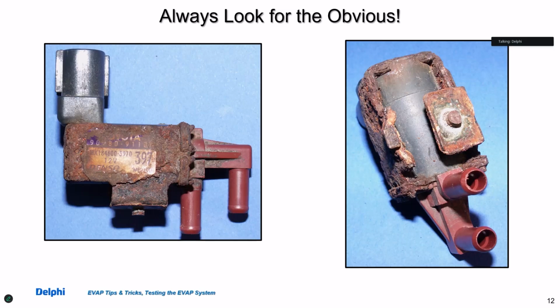Here's an example of solenoids underneath the cars, and hopefully you in the Eastern time zone, you probably Midwest, you kind of chuckle at this because this is a normal occurrence in some cases. Out here, unless you live by the ocean where the salt air is, you're probably not going to experience this at all. We don't have road salts out here or anything like that, but something to look at as you're doing it. Good visual inspection is the first step of a diagnostic plan.